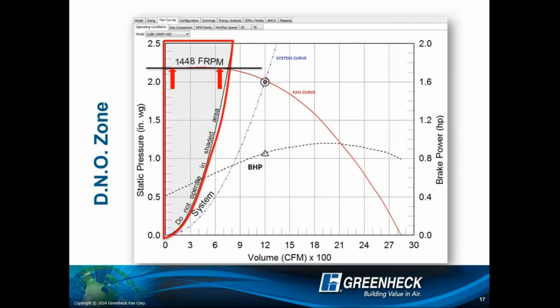A couple more things, like there's stall, surge, there's these different things that can happen. Stall typically occurs when your CFM is too low compared to the attack angle of the impeller, right? Thus, you start losing the ability to push the air forward. This is when you have a much larger fan and a very, very low flow CFM, right? That can cause stall. So there are different things that can happen in this zone, and pretty much every manufacturer is going to highlight this space and say, do not operate in this space. This is not going to be healthy.